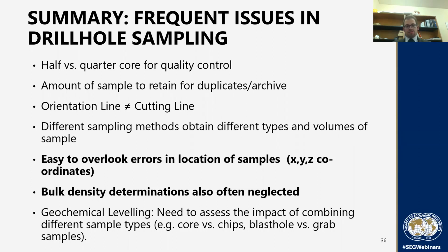A few other issues that are commonly identified is that there could be errors in the location of samples. So if you don't desurvey your holes, if it's an angled hole and you don't obtain the XYZ coordinates through the use of gyroscopes or single or multi-shots, that could lead to erroneous interpretations.